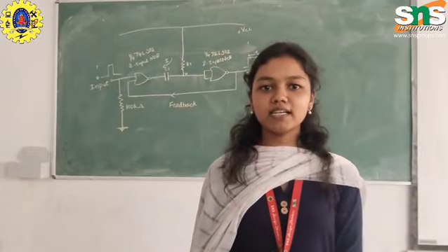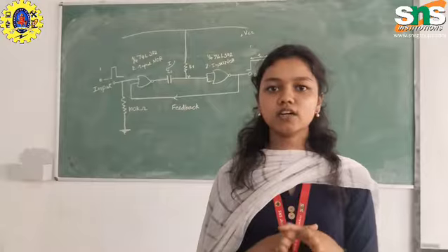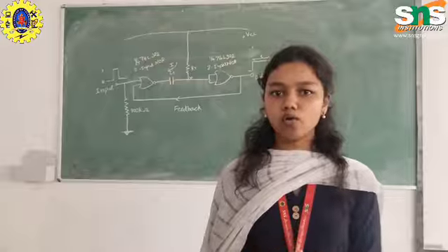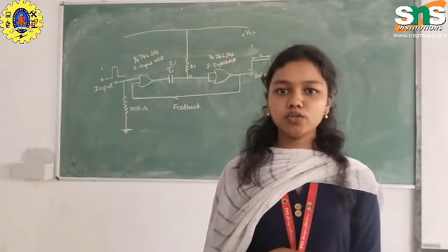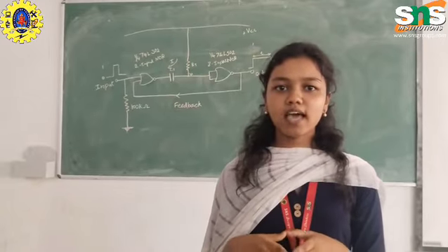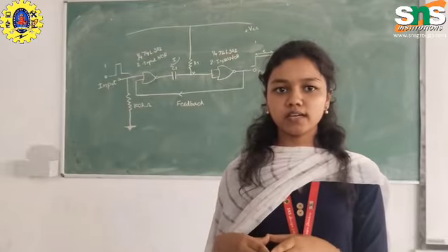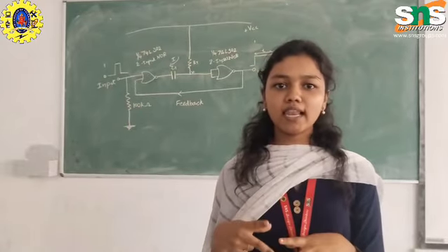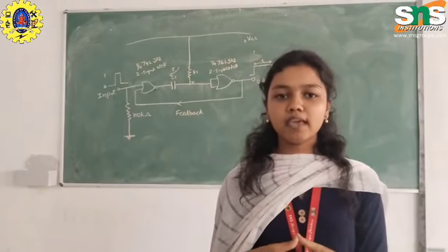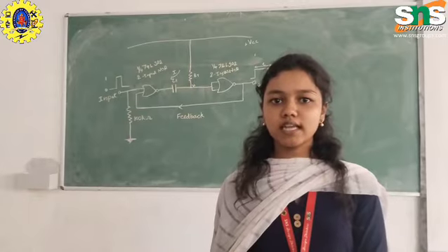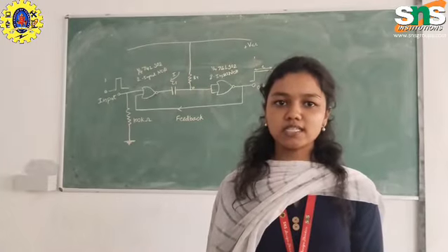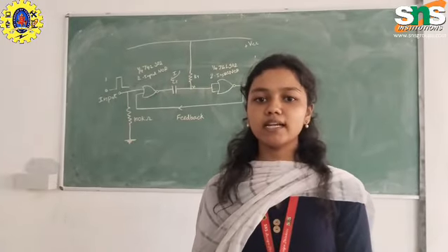Generally speaking, a discrete multivibrator consists of two transistor cross-coupled switching circuits designed so that one of its outputs is fed back as input to the other transistor, with a resistor and capacitor network connected across them to produce the feedback circuit. Multivibrators have two electrical states, an output high state and an output low state, giving them either a stable or quasi-stable state depending upon the type of multivibrator. One such two-state pulse generator configuration is called a monostable multivibrator.